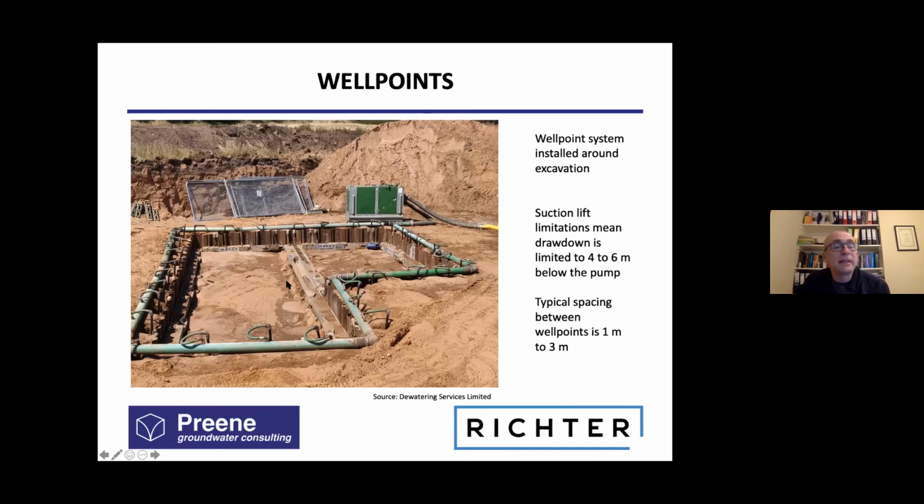A really key limitation of this method is that because it relies on the suction lift principle, the drawdown you can achieve with a single stage of well points is limited to about 4 to 6 meters below the pump. So the most common application of well points is for fairly shallow excavations, maybe for shallow basements or for pipelines. If you need to use well points for deeper excavations, you can use what's known as a multi-stage well point